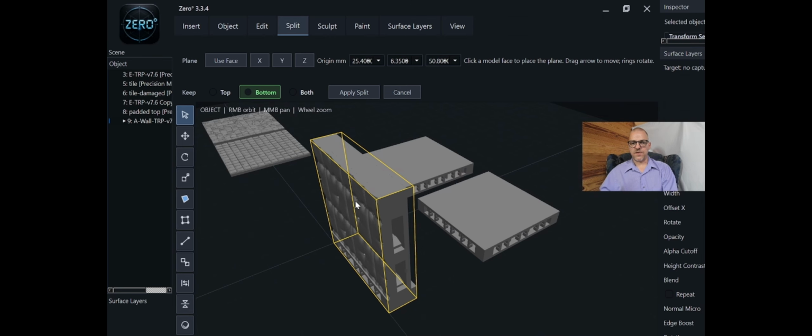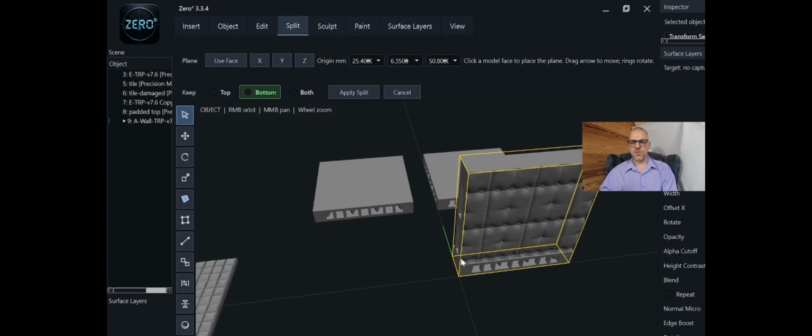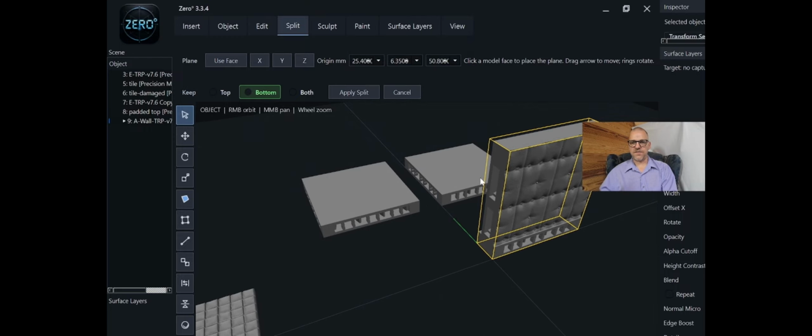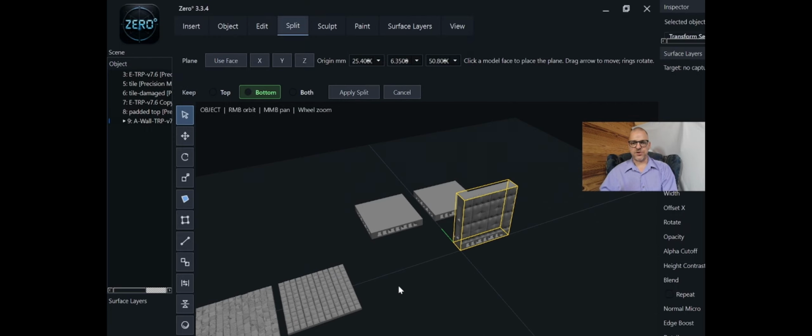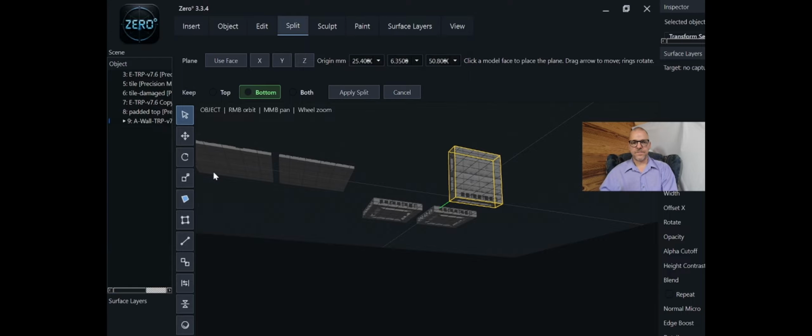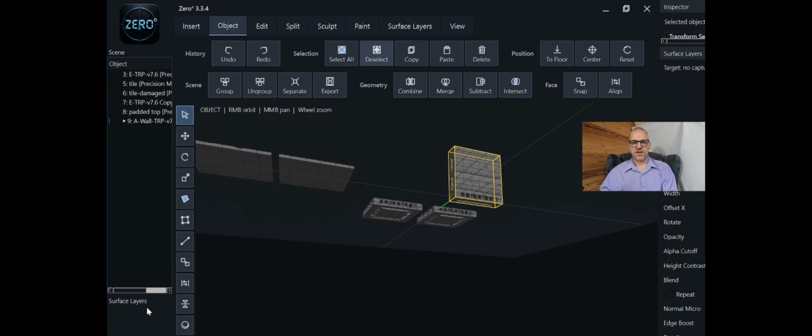Now the reason I got rid of those is because I have some parts with extra clip parts right here through the centers so that they can connect to specialized wall parts that will hold those, so I can do multiple stories with a little more stability and without so much post-processing. So let's get object, select all, snap to face.